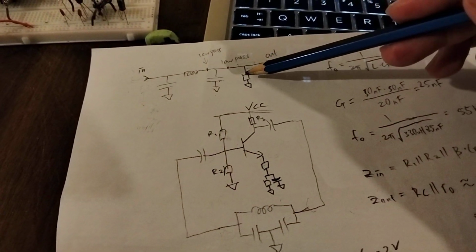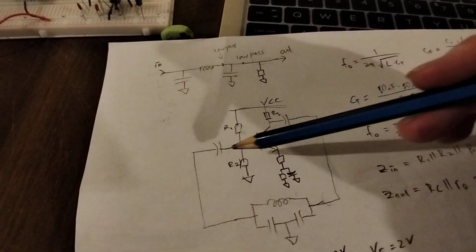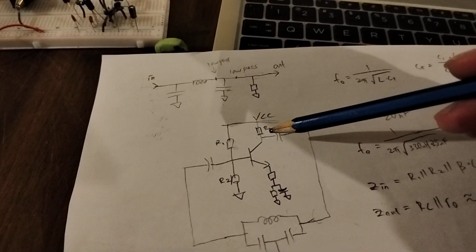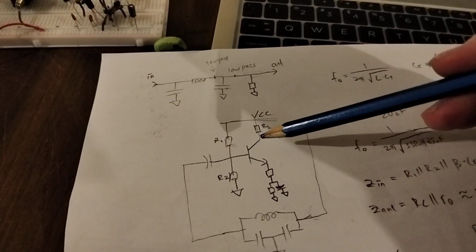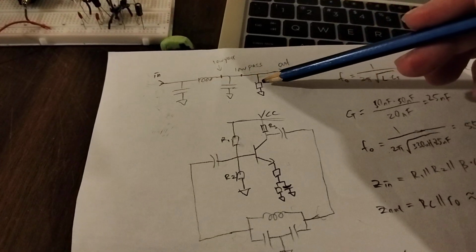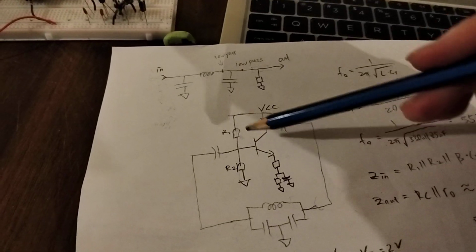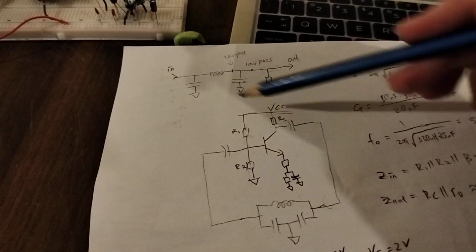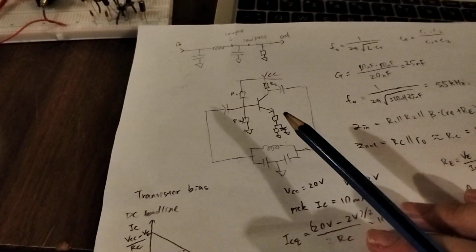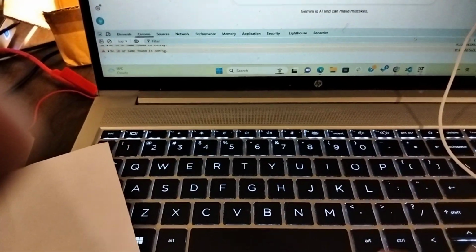And then what happens is the amplifier, right? This amplifier has input and output impedances. The input impedance is actually a resistor to ground, because it's this network parallel to this, parallel to that, and the output impedance is actually these RC capacitors in series. So this filter actually looks like this on the LTspice simulator.